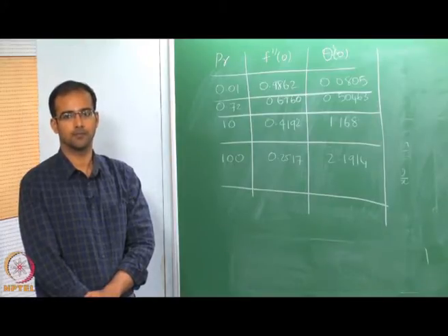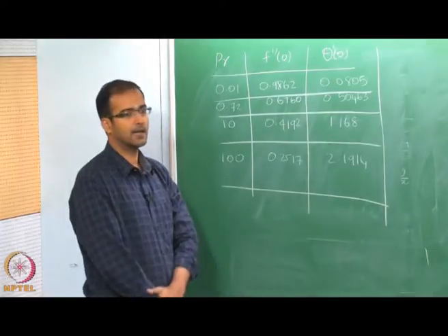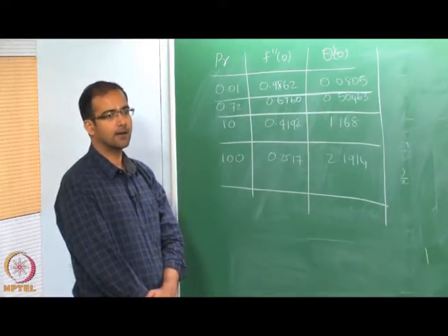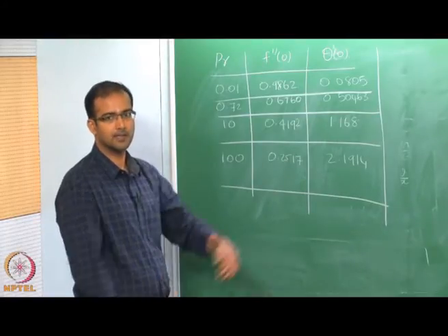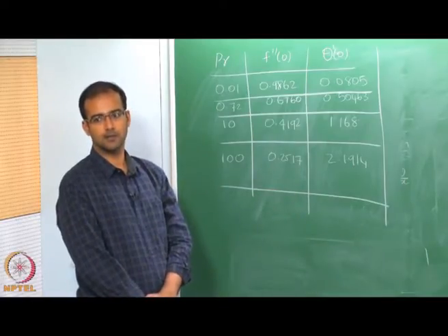That is also the same, 0.332. Okay. So, these values are now slightly higher than that, but it does not mean the final Nusselt number is going to be larger than the forced convection. We will see that. Now, we will convert that into an expression for Nusselt number.